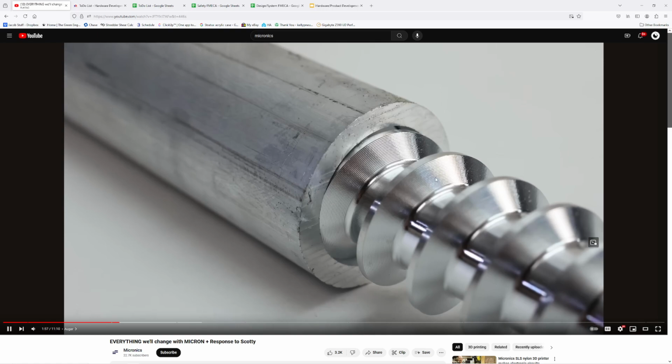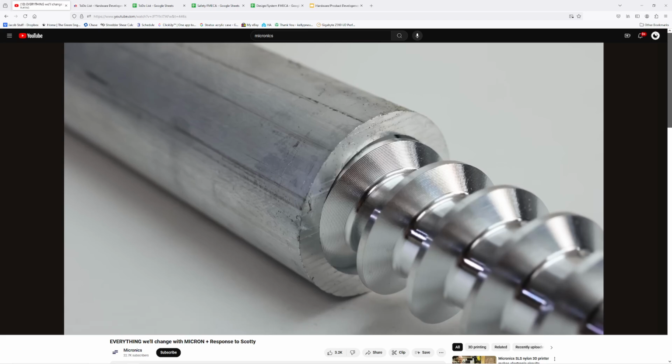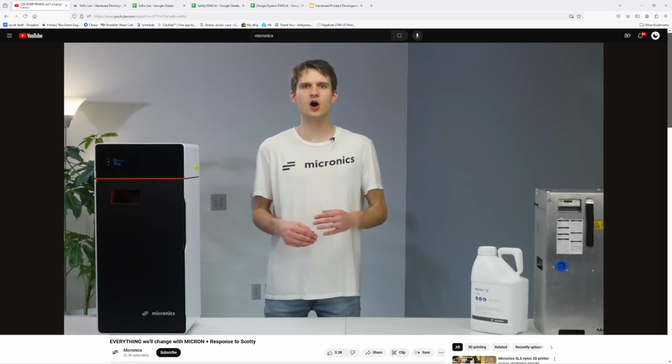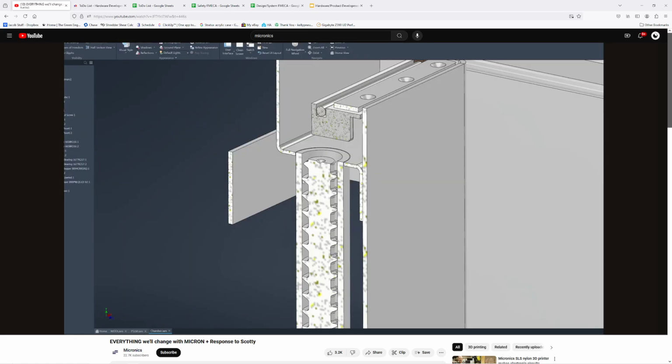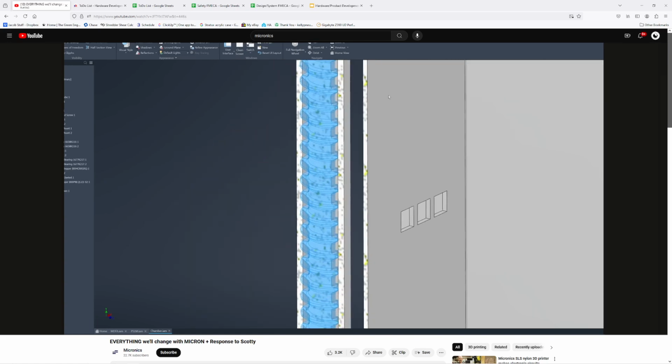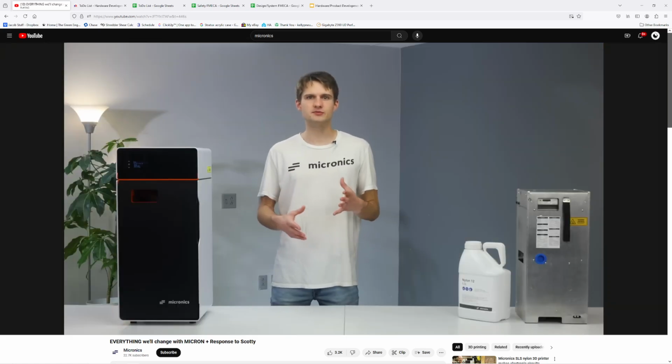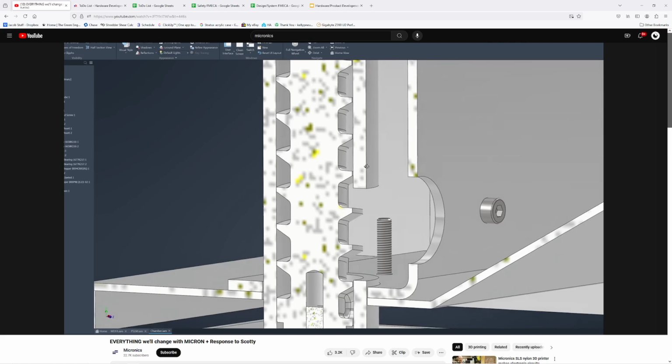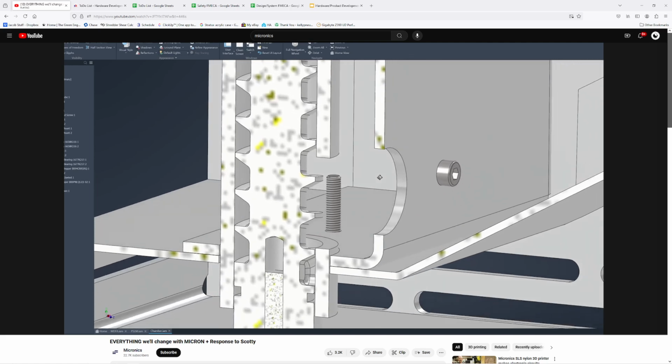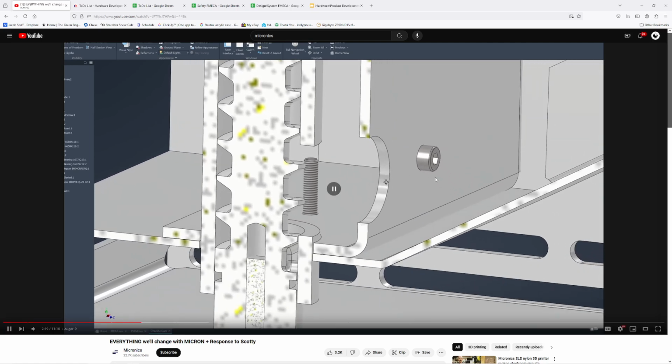Down to clearance. Early on, we had issues with powder leaking back down the auger when the auger wasn't rotating. Our first thought, the clearance between the auger and the tube was too generous, leading to this leakage. By tightening this gap, we managed to solve the problem somewhat, which led us to move on, thinking it's solved. However, we later uncovered the true culprit, which is the auger's inlet was too restrictive.